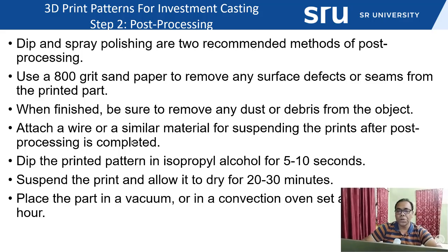Similarly, after that you have to dip the printed pattern in isopropyl alcohol for 5 to 10 seconds, and after suspension the print is allowed to dry for 20 to 30 minutes. Then you have to place the final part in a vacuum so that proper curing takes place, or you can place it in a convection oven set at 440 degrees for 1 hour. You have to ensure proper curing is taking place, otherwise it may be prolonged.